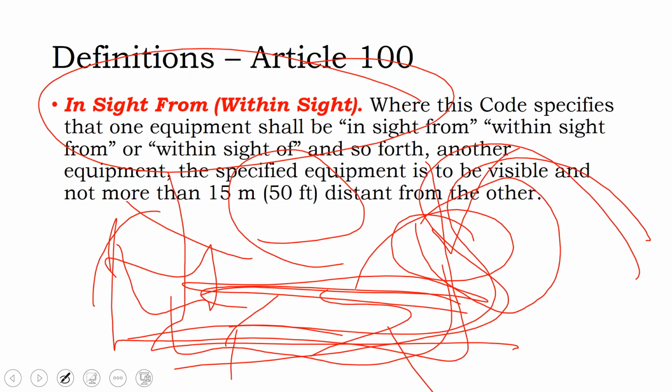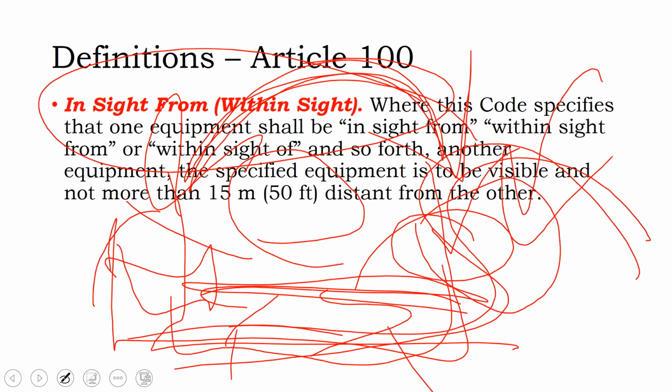Well, having a switch out at your solar array is a good idea too, just from a servicing standpoint. It turns out on this array we turned it on and we had an arc fault connection, and we didn't know where it was in the system. So we had to spend a lot of time marching back and forth between the house and the solar array, manually plugging and unplugging the circuits of the array, which is really not a safe practice for testing, and then walking back to the inverter and reading the screen off the side of the inverter to see, did it clear the arc fault? Did it clear the arc fault? Whereas if we had gone above and beyond code, even though we didn't have to have an additional disconnect at the array itself, if we had just put that additional disconnect there, it would have made servicing easier.